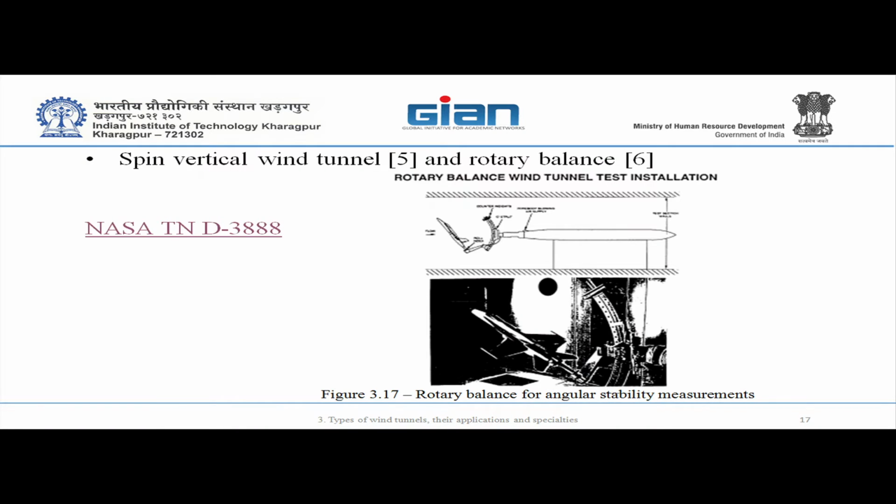Another type of wind tunnels, it's not a type of wind tunnel as it is a type of testing. The regular standard procedure is to calculate the forces and moments. And from there, you can extract the derivatives, first derivatives, static derivatives, to get coefficients for your equations for simulation.